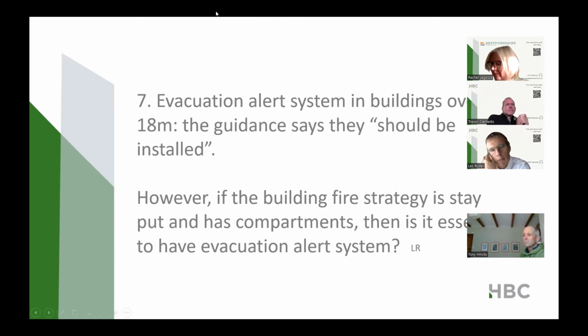And if we go back to fire dynamics and go back to basics, the evacuation policy and the fire alarm are joined at the hip. So as a general rule, if it's simultaneous evacuation, then the fire alarm will be designed in accordance with that. And exactly the same occurs if it's stay put, then the fire alarm will be designed for stay put. And let's go back again to like 1973 to CP3. And this aspect of stay put has always been a relatively new phenomenon, or a relatively new word, I should say.